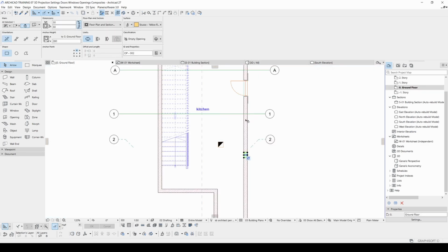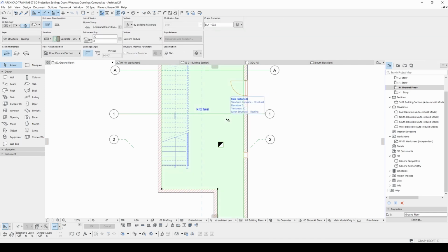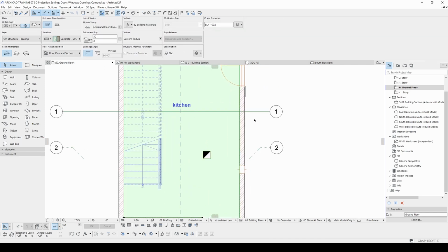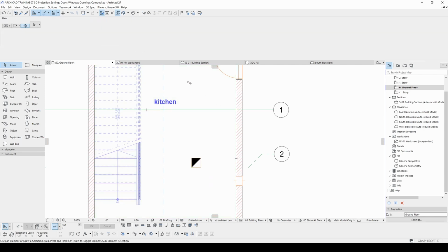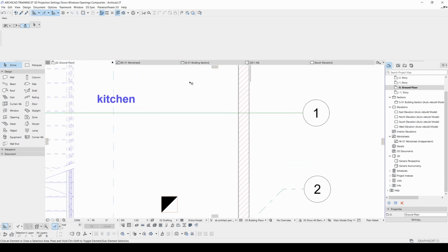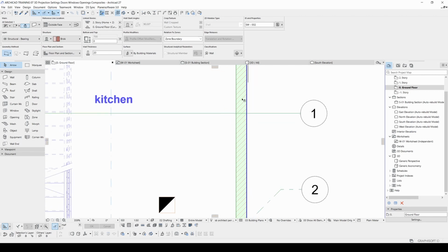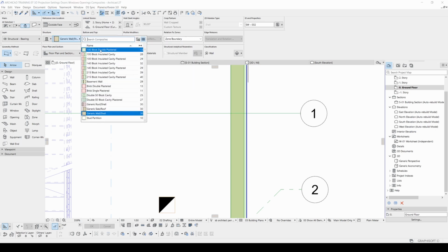Composites are very important while using your walls, floors, and they are visible in sections. Since we see this wall in a section view from our ARCHICAD level, we will see this wall as a section. Therefore, we can add composite to this wall. To do it, we will go to structure and we will click this composite. After that, you will see this composite model from this list.